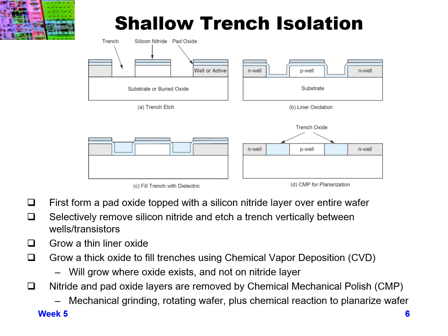So now we'll go through the actual steps in order to produce the shallow trench isolation between P-wells and N-wells. The diagram shown above shows the various different steps. The first two parts of shallow trench isolation are forming a pad oxide. So if we start with a silicon wafer that has the P-well and N-wells already formed, and then of course there will be some P substrate between the wells that will be on the wafer, and we'll have basically a flat wafer.